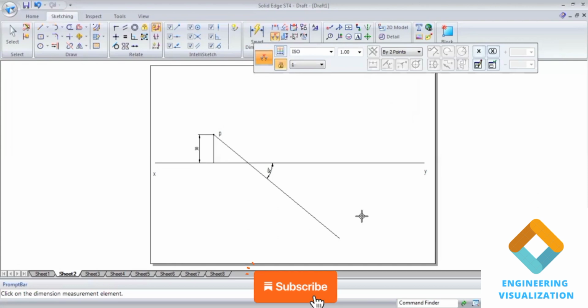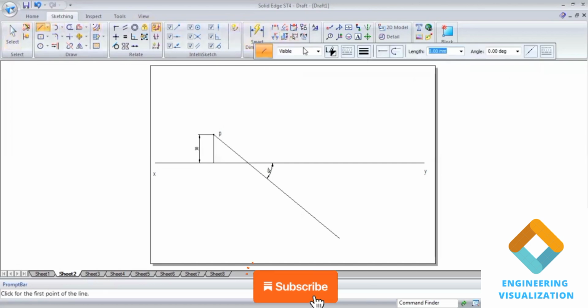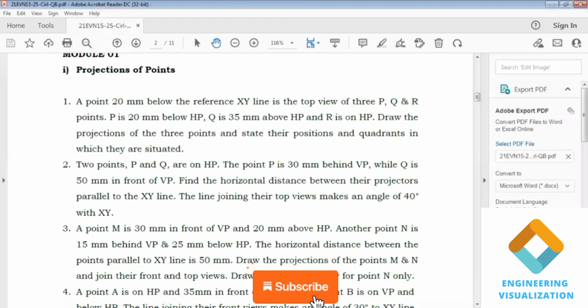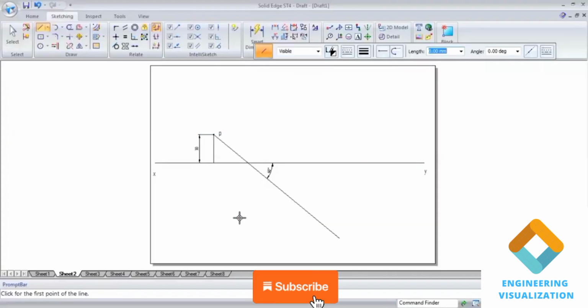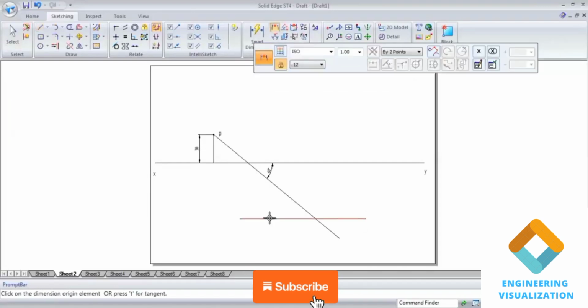Okay, now the other top view, Q, is lying at a distance of 50 mm. So I will draw one parallel line here, parallel to the XY at a distance of 50. Just draw a line and then using the distance between command I will change it to 50.